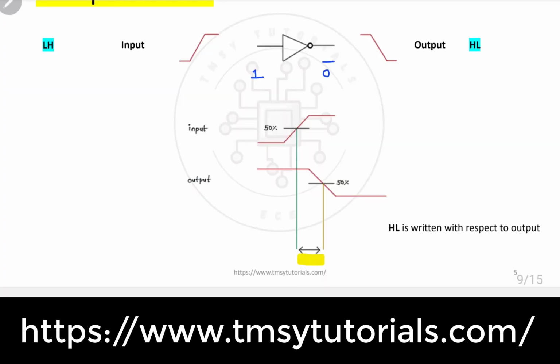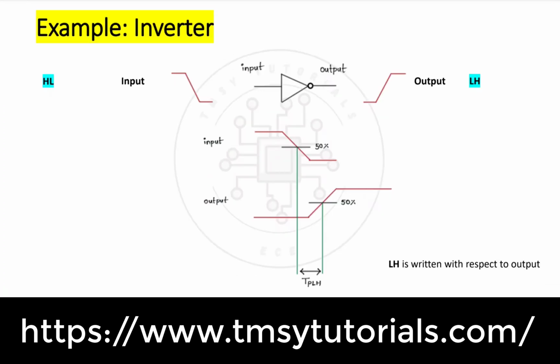Here we are writing TPHL, high to low. Why? Because the output is changing from high and coming to low. It should always be considered at the 50% value, high to low. Now we apply the input to the inverter from high to low, so the output will be from low to high.